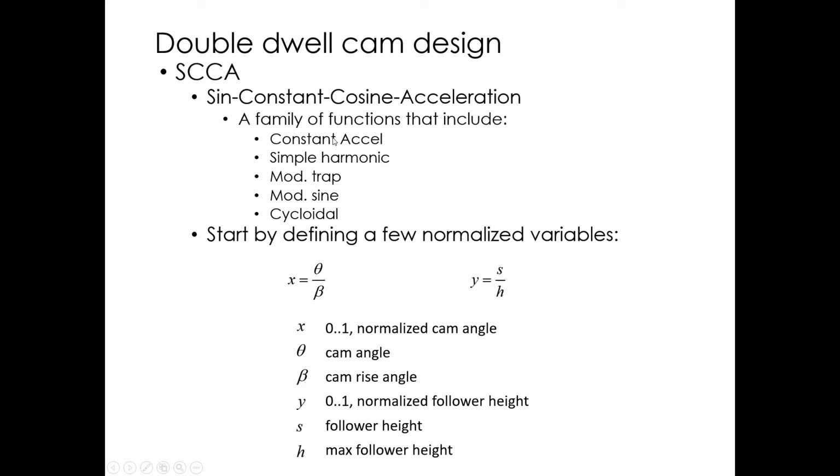So that's where SCCA comes in. SCCA is a family of functions that are built up piecewise that let us model all sorts of different cam profiles, from constant acceleration to simple harmonic motion to modified trapezoid, modified sine, and cycloidal. Mod sine we haven't talked about.